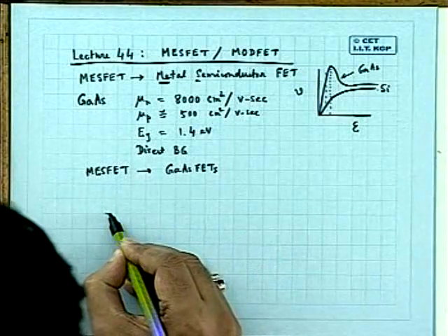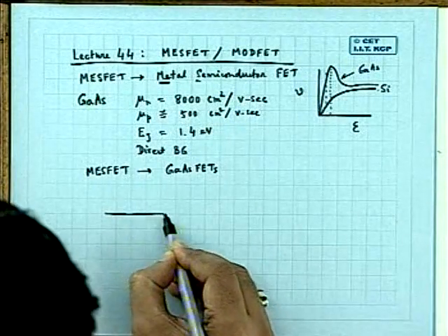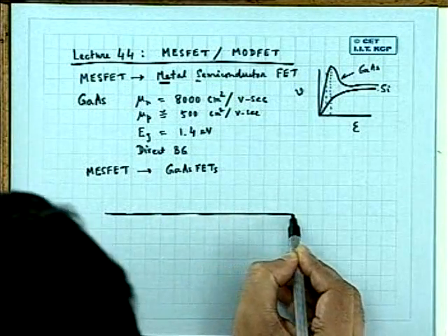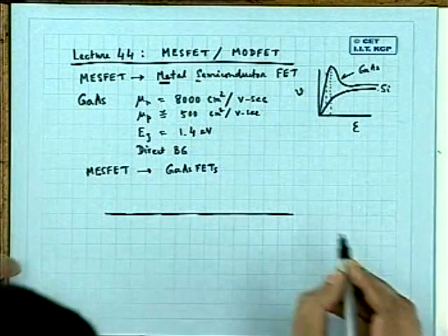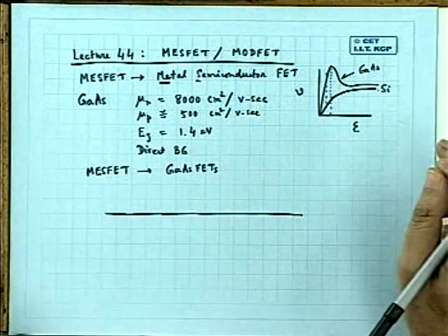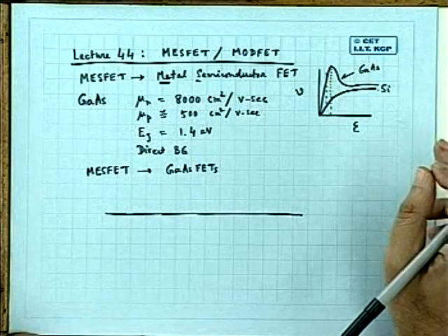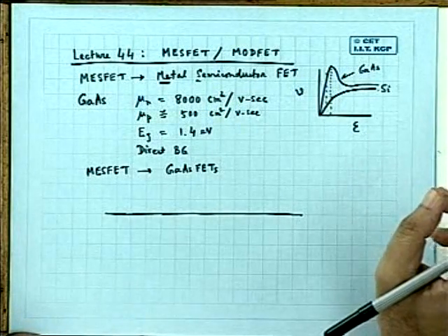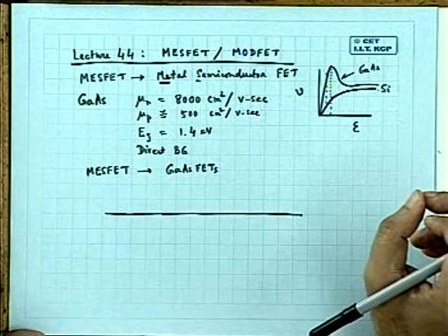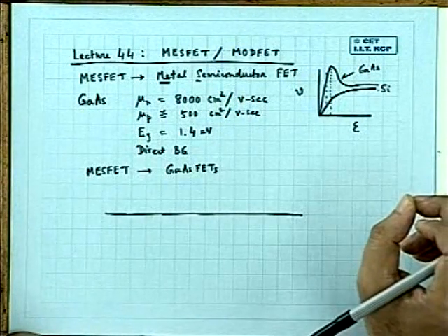It is nothing but a JFET, a little bit different. It's a MOSFET-kind of device with a Schottky gate. A typical gallium arsenide MESFET looks like this. You know the advantage, one advantage of gallium arsenide which silicon does not have, is as follows. We can get gallium arsenide in a very high resistivity form.